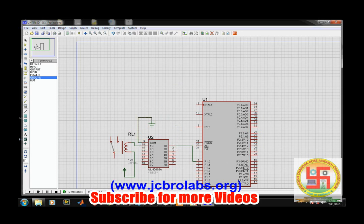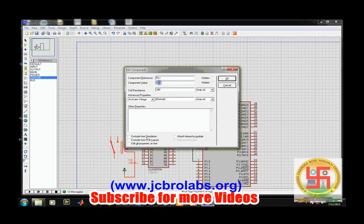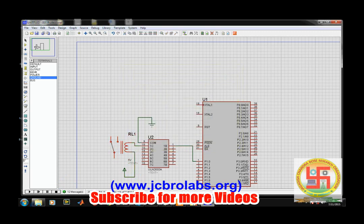And let's connect here ground. Let's see if it is working. Yep, it is working. But the thing is, when it is +5, when this is +1, output is 0. It's fine, but the relay setting is there, so let's make it a 5V relay instead of 12V. Now let's see. Yes, so when 1 is there, it is on, and when 0 is there, it should be off.